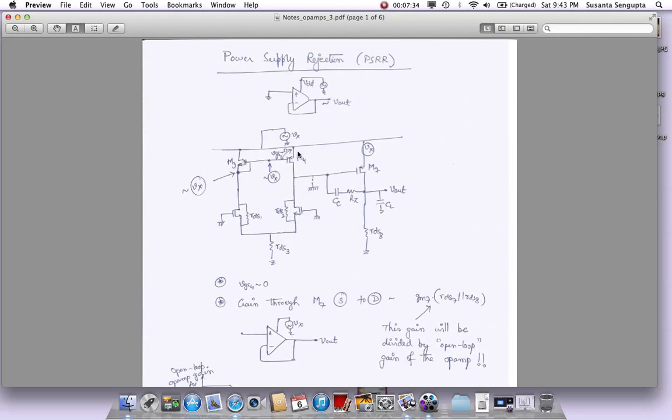right? So it is not able to create any current, but see, there is another resistor here. Yeah, I should not say it's AC ground exactly. It will have some voltage. And why will it have a voltage? Because remember, this M4 has an RDS also there, right?